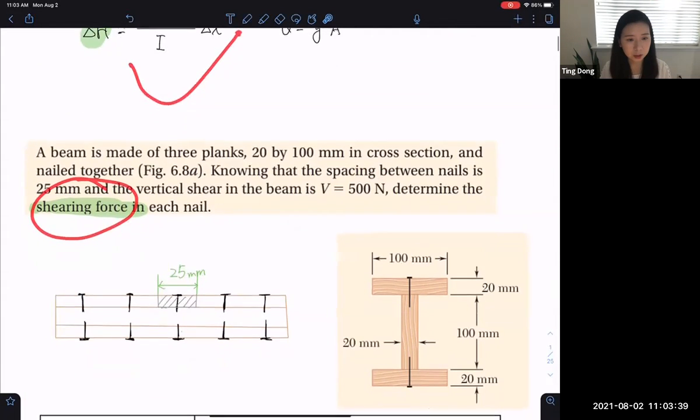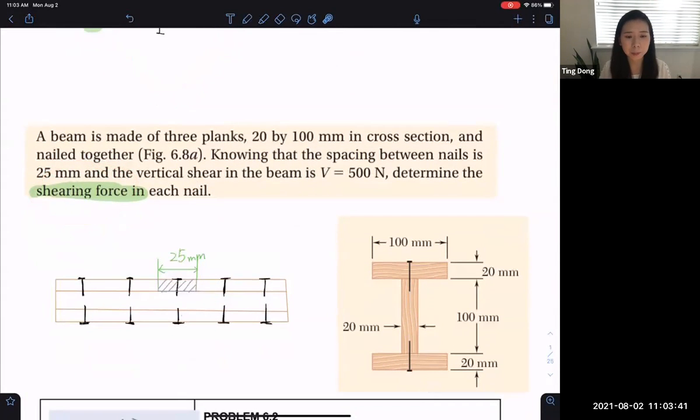So basically, we use this equation directly and calculate the shear force. Of course, the shear force carried by the nail is the shear force generated here. As I said in class, for this type of problem, when we consider Q, we imagine that we separate the entire cross section into 2 parts through this cutting surface. Now we have either this area or the rest.